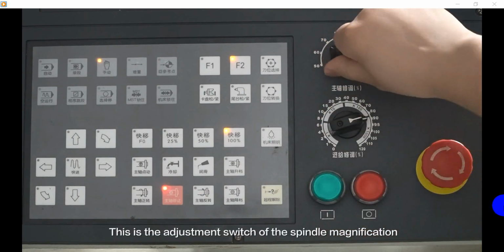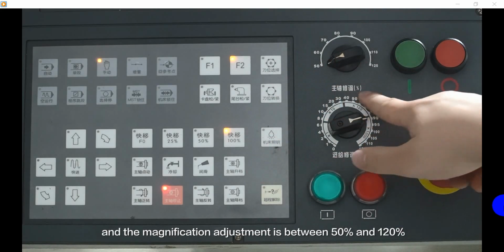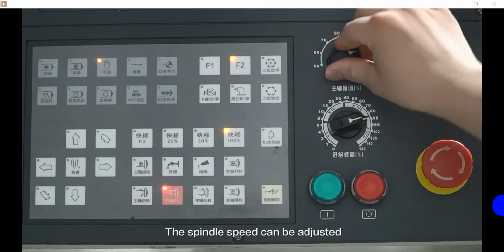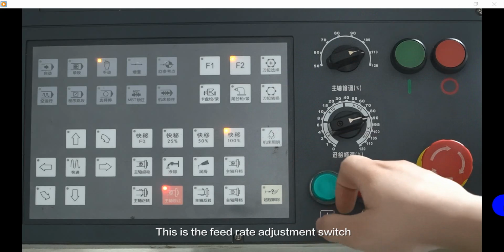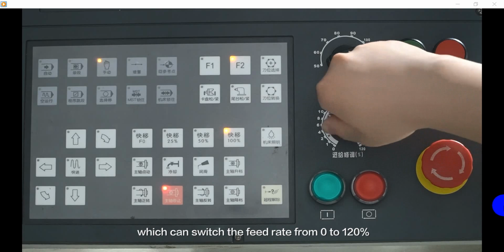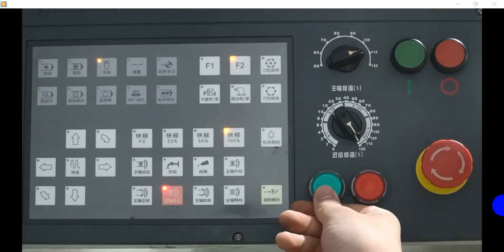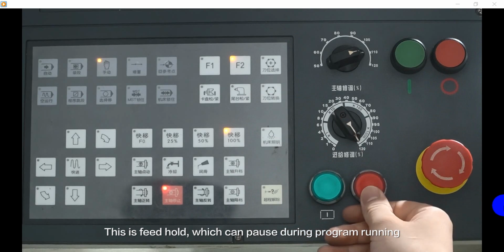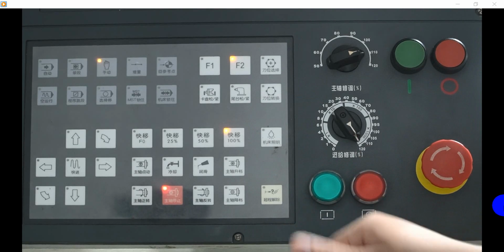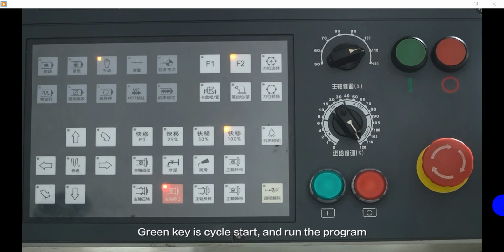This is the adjustment switch of the spindle magnification, and the magnification adjustment is between 50% and 120%. The spindle speed can be adjusted. This is the feed rate adjustment switch, which can switch the feed rate from 0 to 120%. This is the feed hold, which can pause when the program is running. The green key can start the cycle and run the program.